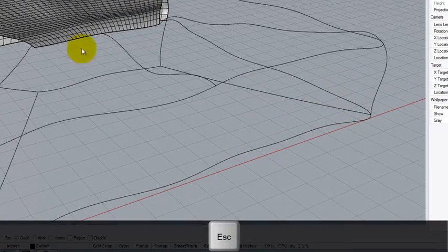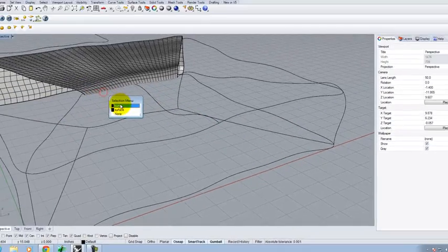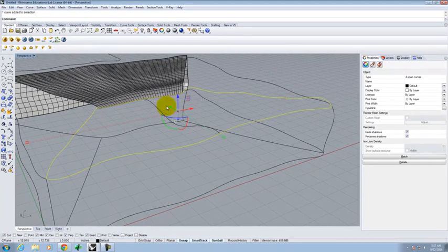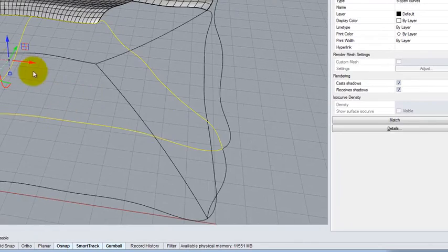And so I have this. Now when I do a curve network, just like I did before, I'm going to pick each of these edge curves that go around, but I'll also pick this one in the center. I could add another curve that goes across this way. The key is when you start to have additional curves, if they cross, they have to cross at the same point. You can't have one curve going this way and one curve going this way where there's a space in between. If you're creating a network of curves, they have to match up at each intersection of curves.